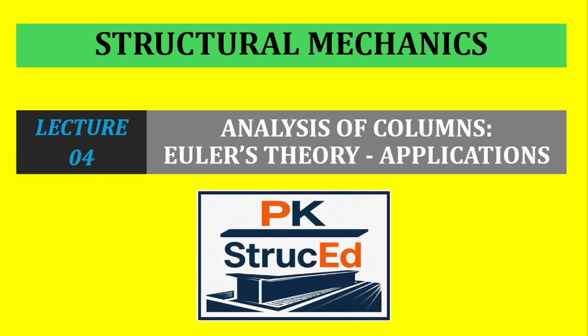So through this example, we will understand how to identify the correct end conditions, how to compute the effective length, as well as how Euler's formula is used to find the safe load, critical load, or the geometric parameters. This is lecture number 4, and the topic is analysis of columns, in which the application of Euler's theory has been used. All problems discussed today will involve long slender columns where failure occurs by elastic buckling rather than crushing.